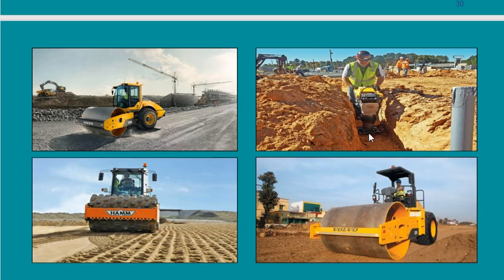This is the same for a small area. If I have a small trench, I cannot just put this equipment inside this small trench. So I have to bring smaller equipment, and in this case, vibration should be higher because I will depend mainly on vibration, because the weight of this small equipment is very, very small. So I need something to be very, very strong in vibration.